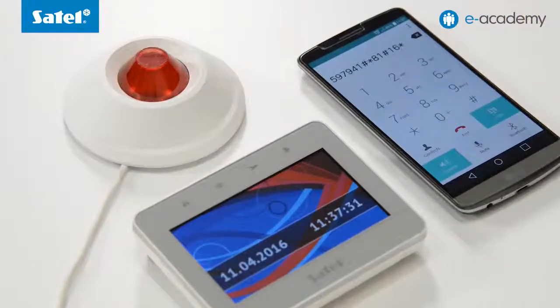Inactive. 1. Macros. An interesting function offered by the INT-VG module in the Versa Plus control panel is audio monitoring. It enables alarm verification by listening into the sounds from the location where the control panel is installed. To make use of this functionality, you must connect the INT-AVT acoustic alarm verification terminal to the control panel.